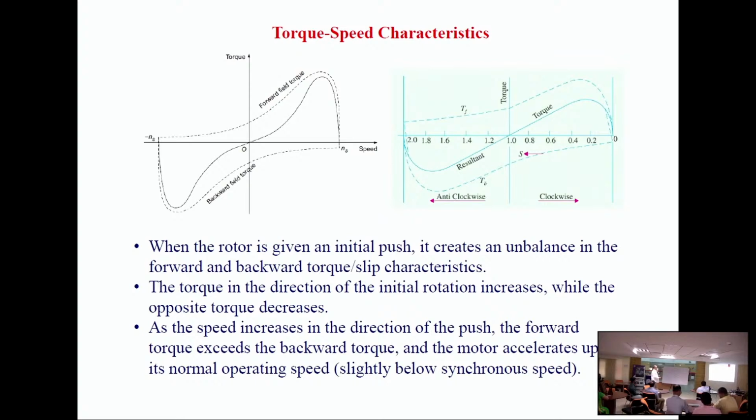Okay. So as the speed increases in the direction of push, the forward torque exceeds the backward torque and the motor accelerates up to its normal operating speed, which is slightly below synchronous speed.